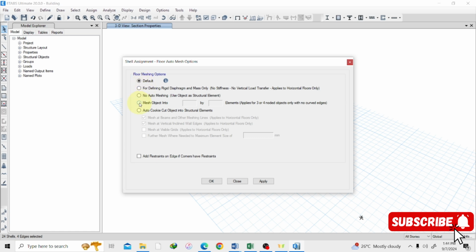So I'm just going to check this box, mesh object into. With this one, you are just going to divide the slab into various sections, maybe 2 by 2 or maybe 1 by 1. It really depends on you. I'm going to go for 2 by 2, just like this. Or I can also decide to choose auto cut object into structural elements. With this one, you select the ways you want the mesh to be.